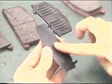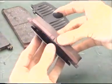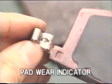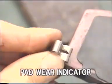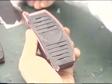Apply grease to the anti-squeal shim and assemble to a new pad. Install the pad wear indicator plate to the inside of the new pad. Be sure that the arrow on the pad wear indicator plate is pointing in the direction of rotation of the rotor disc.